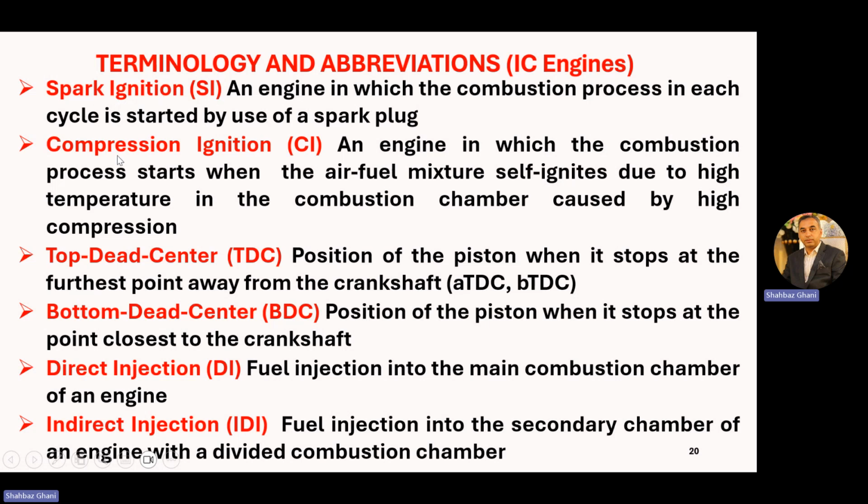And the other form, the compression ignition, CI engine, an engine in which the combustion process starts when the air-fuel mixture self-ignites due to high temperature in the combustion chamber caused by high compression. So remember this: in a compression ignition engine, we don't have a spark plug, but we get the ignition of the air-fuel mixture due to self-ignition. And that self-ignition is due to high temperature and high pressure in the combustion chamber.